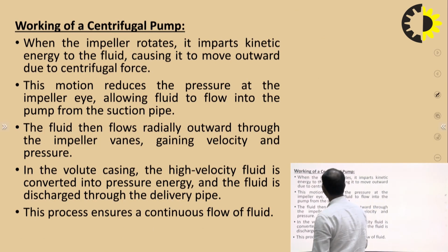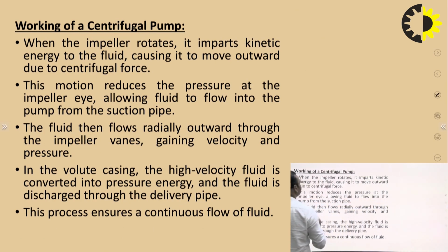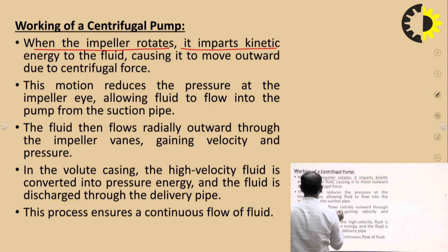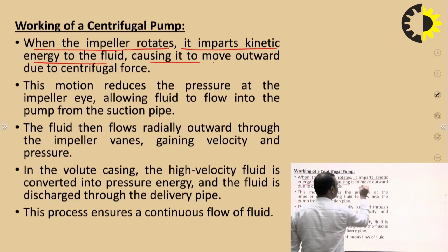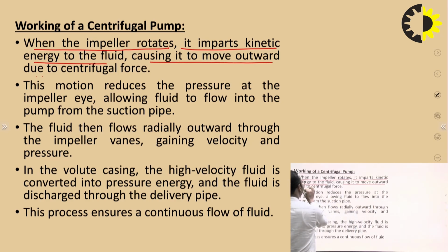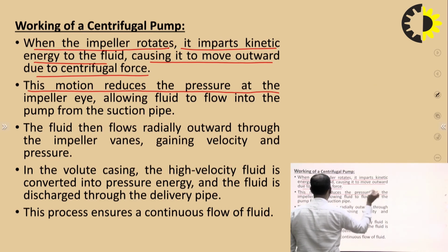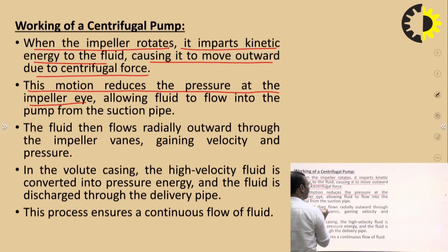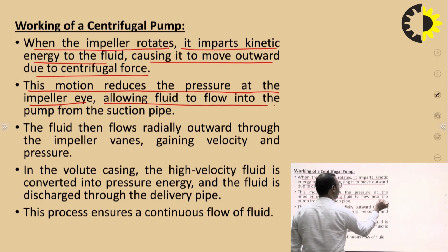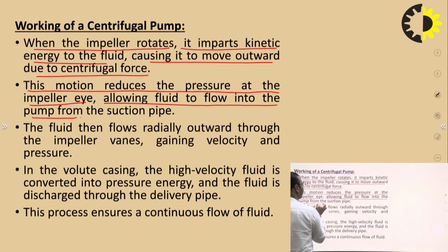Then what is the working behind the centrifugal pump? When the impeller rotates, it imparts kinetic energy to the fluid, causing it to move outward due to centrifugal force. This motion reduces the pressure at the impeller eye, allowing fluid to flow into the pump from the suction pipe.